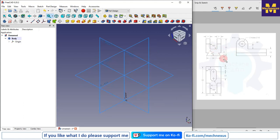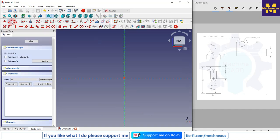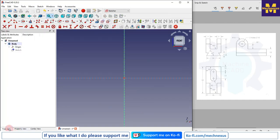So this is the front view and this is the bottom view because it is a third angle projection, and this is the side view. So first we will make the side view, so that will be the easiest way to model this part. So for this I will select this plane and I will create a sketch, and I will move to the tree view and I will select my origin and press the space bar.